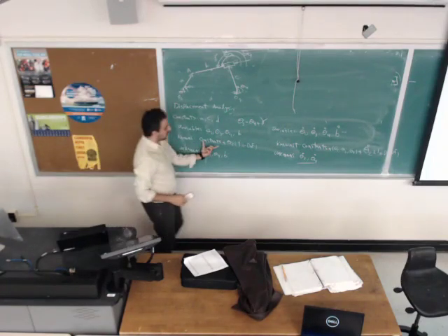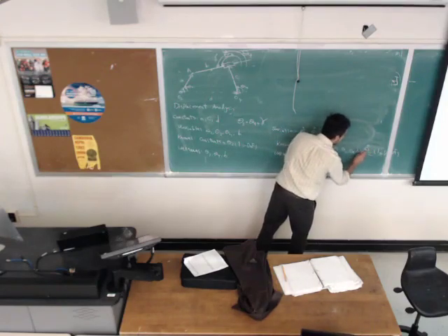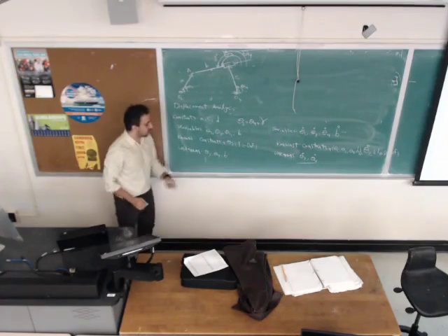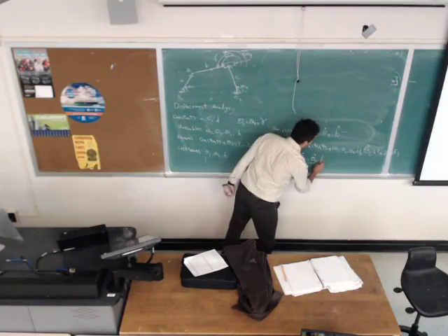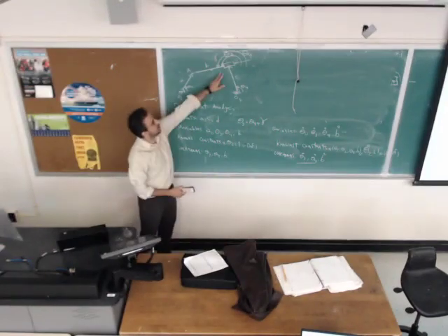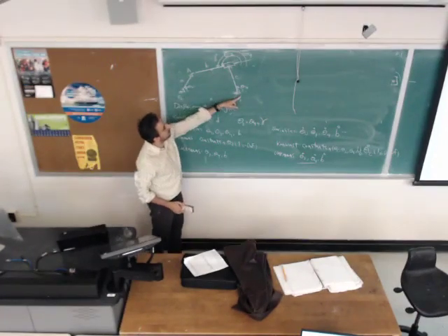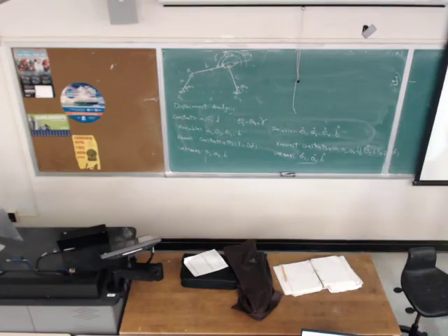The knowns are the constants plus theta 2, theta 3, theta 4, b, and theta dot 2, and we are solving for these three: the velocity of the slider, the angular velocity of link 3, and the angular velocity of link 4. So we are going to do this tomorrow.